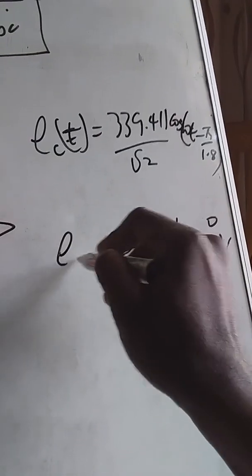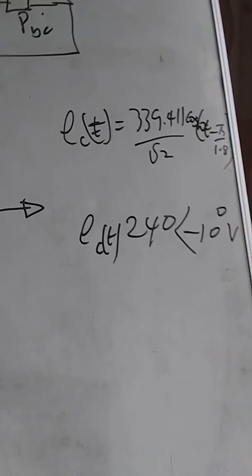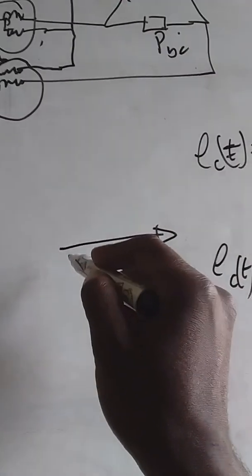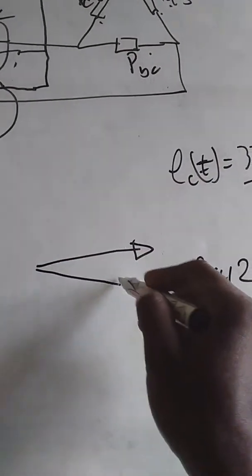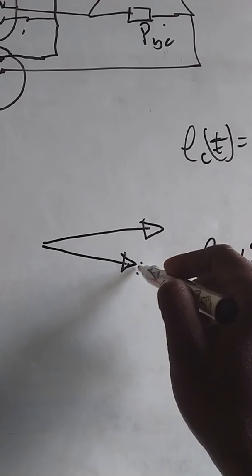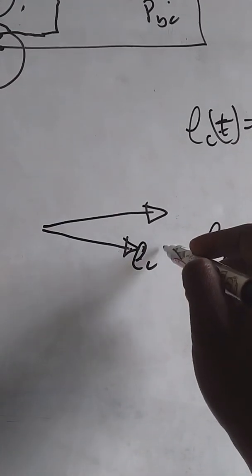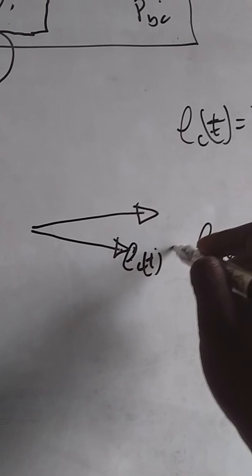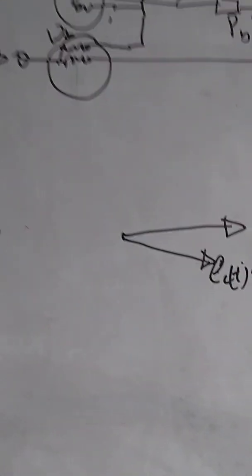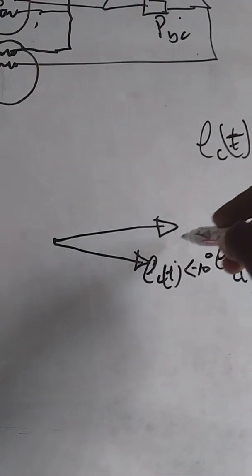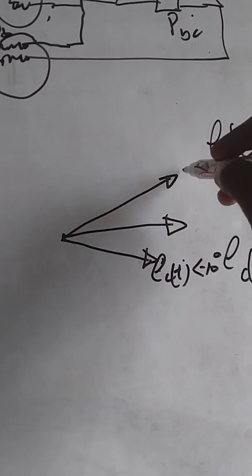So that is the phase voltage, which is the reference. So it's at minus 10 degrees. So where is minus 10 degrees? Let's put our minus 10 degrees to be here. Let's say our EC is at minus 10 degrees here. Then because it is positive phase sequence, line leads. So that means line leads by 30 degrees. So here will be ECA at angle 20 degrees.